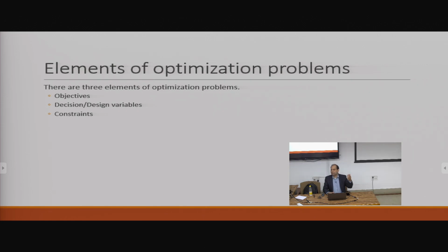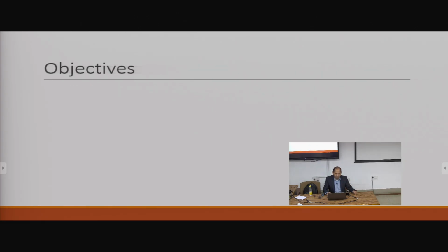And sometimes you would have unbounded solutions. It'll say, oh, you know what? You can keep increasing profit if I just keep increasing that number. I can save you a lot of money if we didn't build the aircraft wing. So when you say cost optimization problem, if you don't have that constraint, then it'll say, okay, well, don't build it. Anyway, for a properly modeled problem, for an aircraft wing structure, if you reduce the cost beyond a certain point, you reduce material enough that it becomes weak. So sometimes you can impose constraints that way.